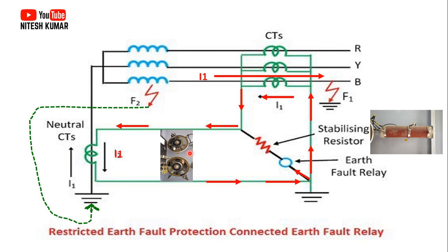Practically, you will see it in the control and relay panel, where it is called the metrosil. How it works: if the voltage exceeds, the temperature in this material will increase, and the resistance will decrease. If the resistance decreases, in such a way this will surge the voltage.